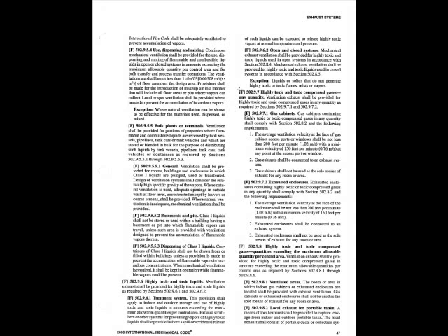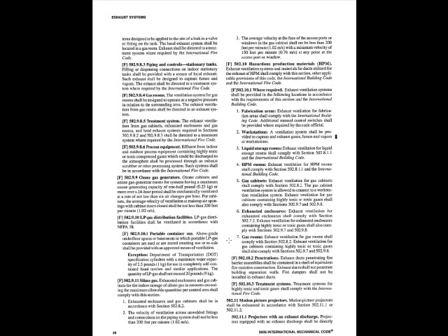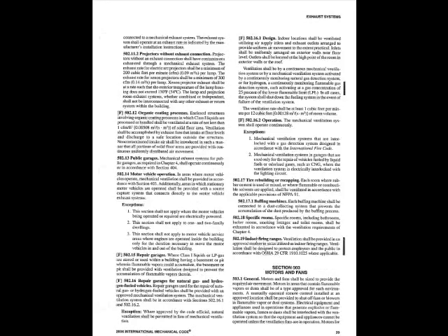Then we move on to highly toxic compressed gases. What's required for the gas cabinets, how much exhaust in feet per minute or feet per airflow. Exhaust enclosures. How do we protect the actual exhaust systems? We continue to move through here, and every one of these areas in 502 has something to do with a specific material. So if you're doing anything in terms of building, or if there's a change in occupancy or change in purpose, you need to take a look at section 502.